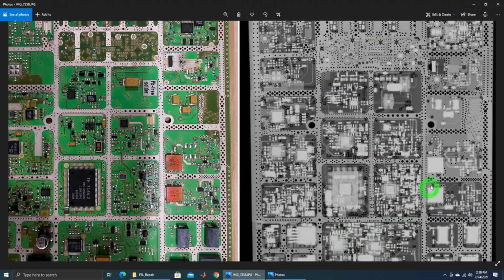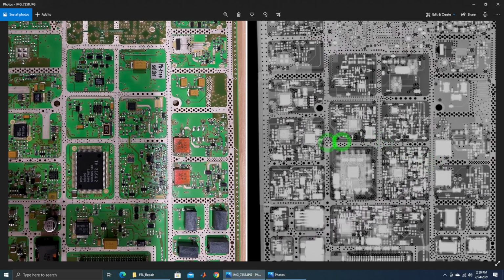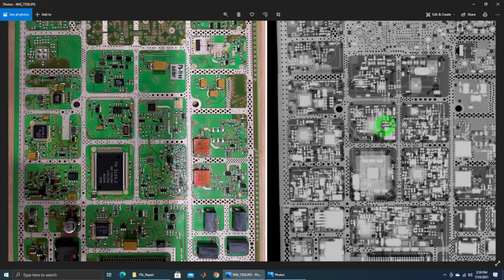If you go back a little bit again, try to follow the part of the PLL, which is the problem we're trying to look at. This guy over here is our VCO. This is a 3.1 to 3.5 gigahertz VCO, again from Hittite. You can see the signal coming over here, it gets amplified, and then it gets split into multiple places because you need to feed different sections and even divide them and get to the other mixer so that you can get the final IF. And if I look here, you can see some of it coming back over here, feeding onto this side.